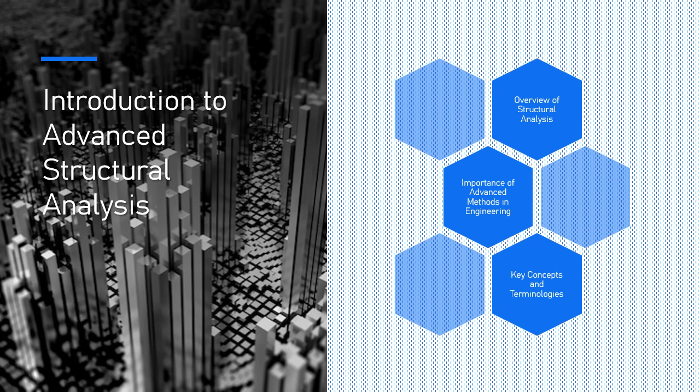Measures deformation. It's often used to assess whether a structure will remain functional under load or whether it will experience failure. For example, beam deflection under loading is one of the common displacement analyses done in structural design. In advanced methods like finite element analysis, FEM, displacements are calculated at numerous points, called nodes, across a structure to simulate real-world behavior with high accuracy.